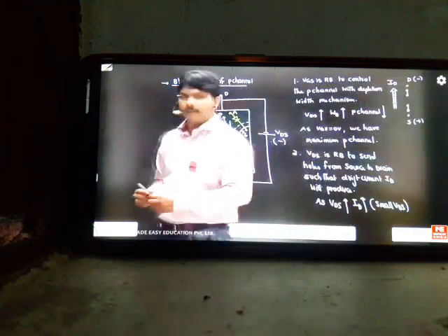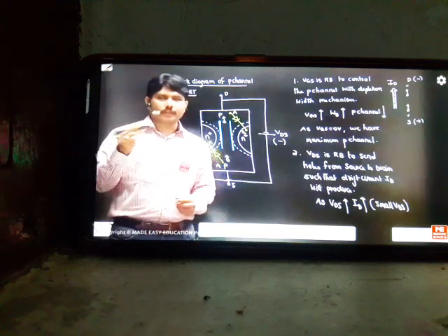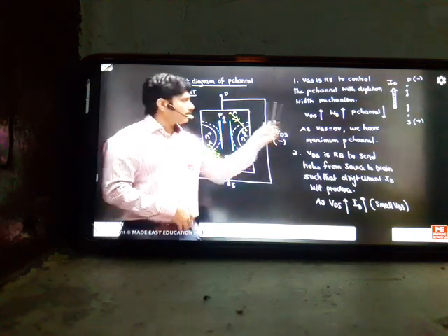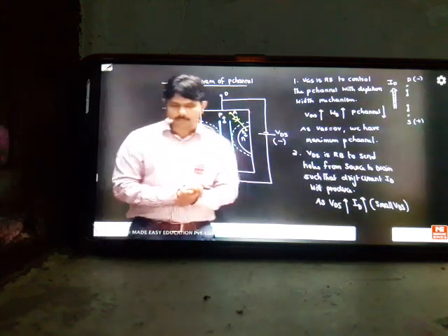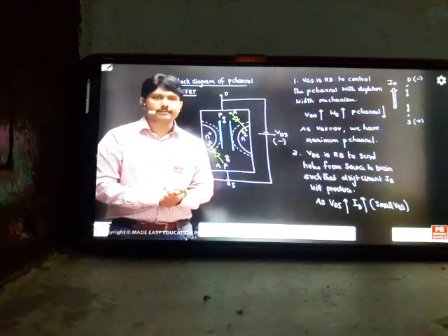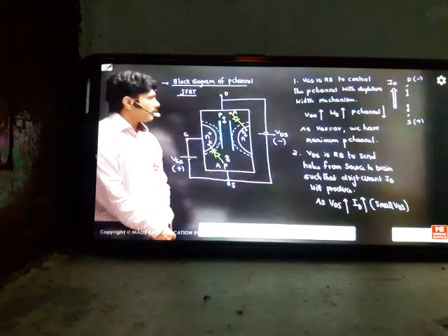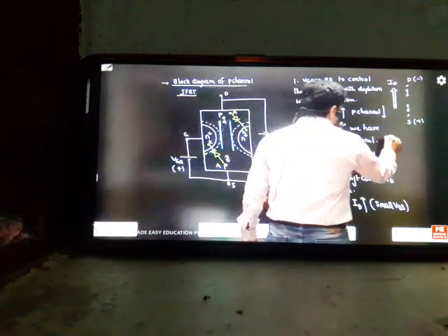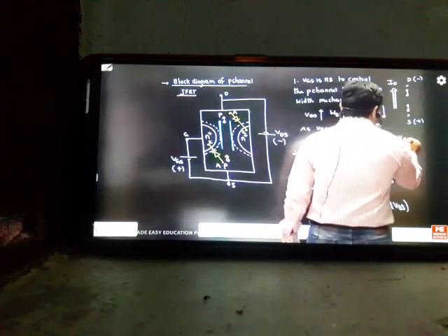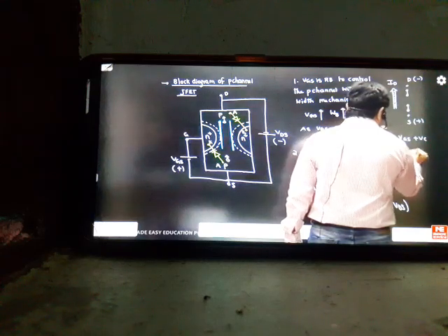So the only difference in the current flow direction is, for electrons when they are moving from source to drain, the current direction I've shown you top to bottom. But for holes, the current direction should be parallel we have to take. That is the difference. Because holes are considered to be positively charged particles, the current direction and the hole movement will always be the same. As well, the direction of current will go upward now in P channel devices. All the things I covered. Only one issue is point number 3. Notation signs you can see. One is VGS notation should be positive we have to take, and VDS notation we have to take as negative.